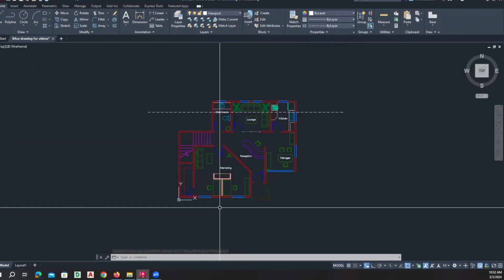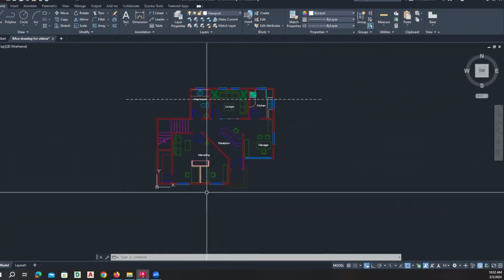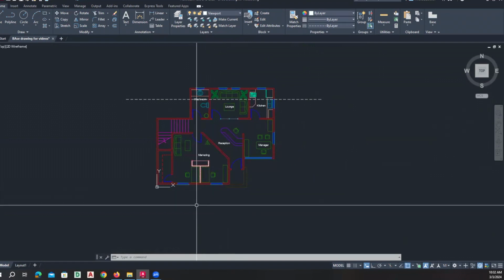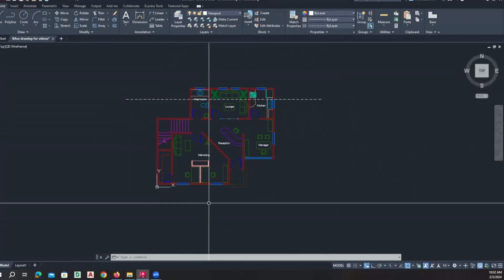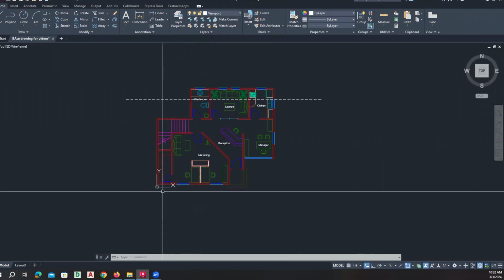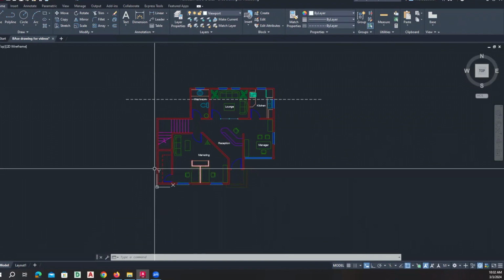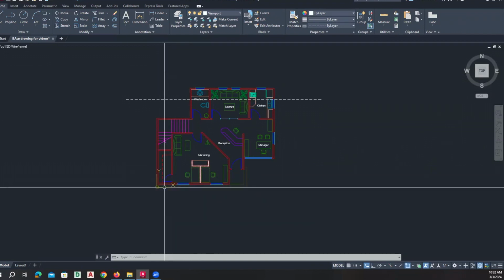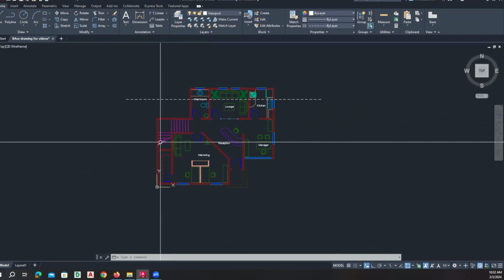Something that I would also like to talk about is once we rotate the UCS, how do we actually orient our drawing to be parallel to that specific UCS? So for instance, my WCS is oriented as it is now, X across the bottom and Y going vertical.